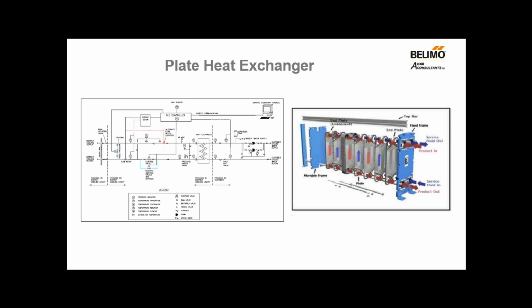Oversizing reduces valve life and causes the valve to hunt. Control valves should be selected with high rangeability, low leakage, and proportional plus integrating control for close adjustment, accuracy, and response time.